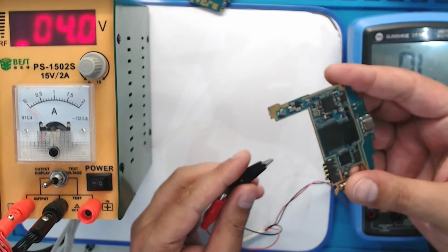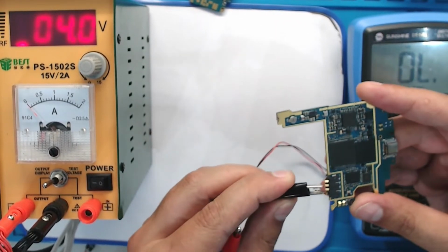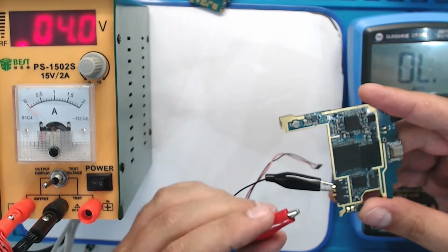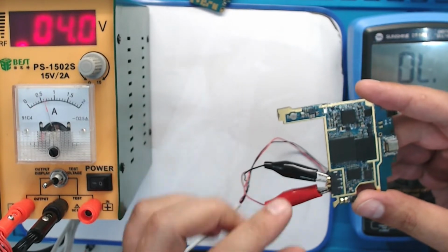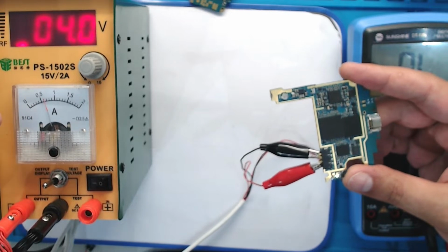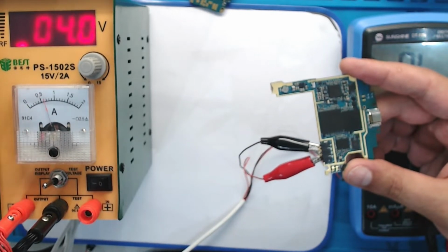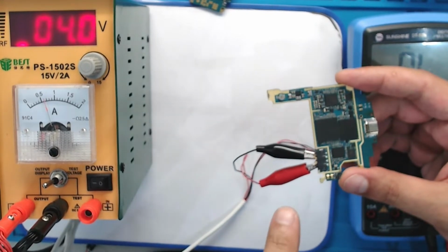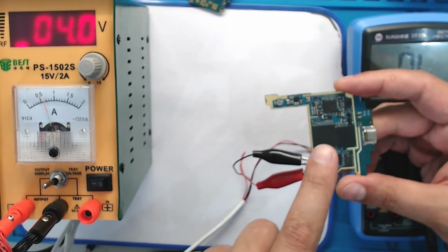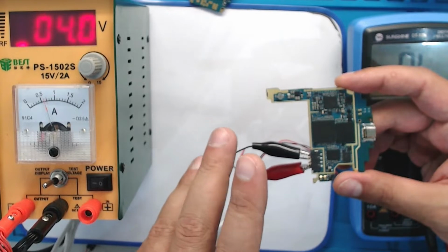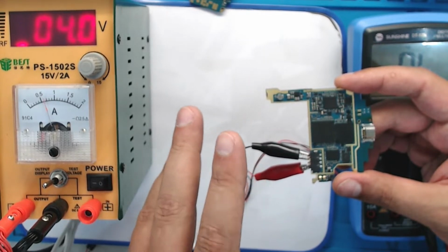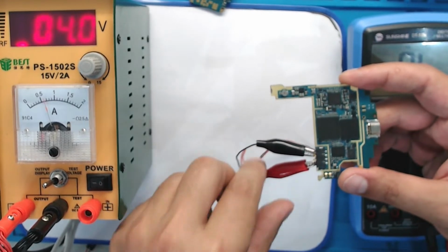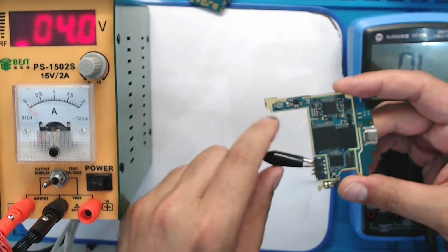But you see this one, I connected it, and before pressing the power button, it shows leaking of around 600 milliamps. That means this one has a large leaking current. This is an abnormal phone. Usually the issue can be found by voltage injection. That's in the voltage injection video, where I'll tell you how to fix this issue.